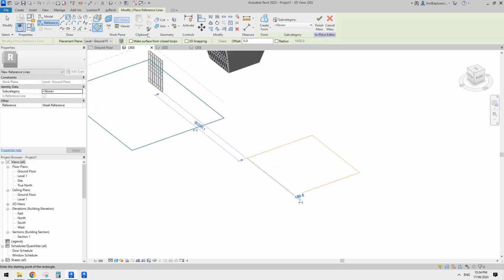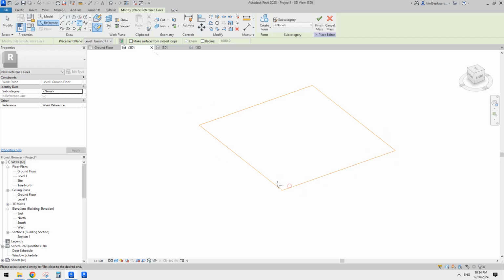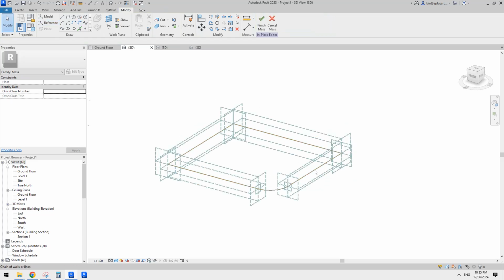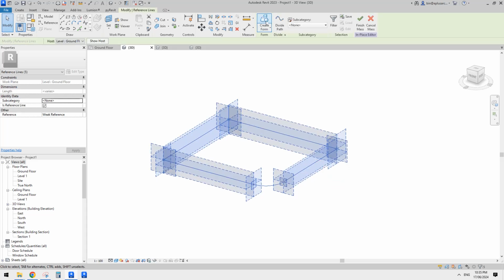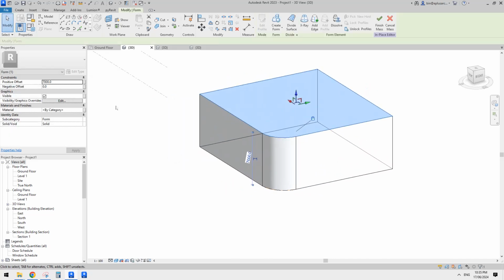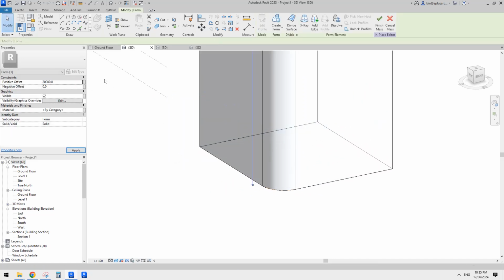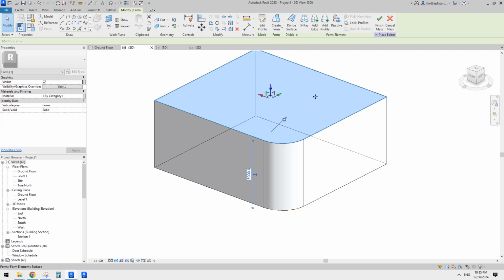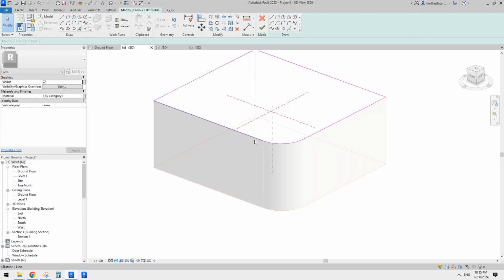And then I'll want to use fillet arc to create a corner. Maybe 3 meter, for example. Okay, so I think that's good. Yeah, I'll just create a form from this one. So it's like an extrusion. Once you create this one, I'll make it 8 meter. Oh no, sorry, not 80 meter. 8 meter. And you can just unlock this one and use edit profile and change this.